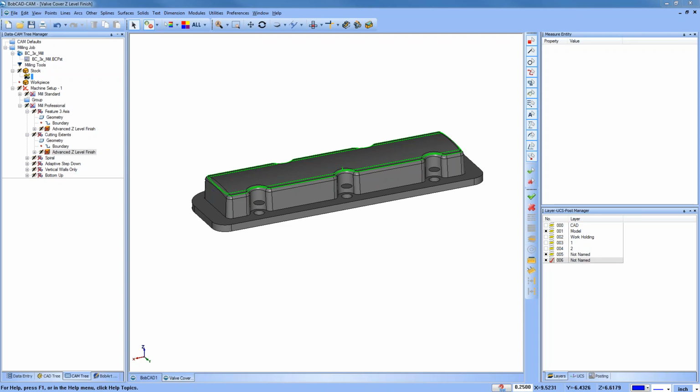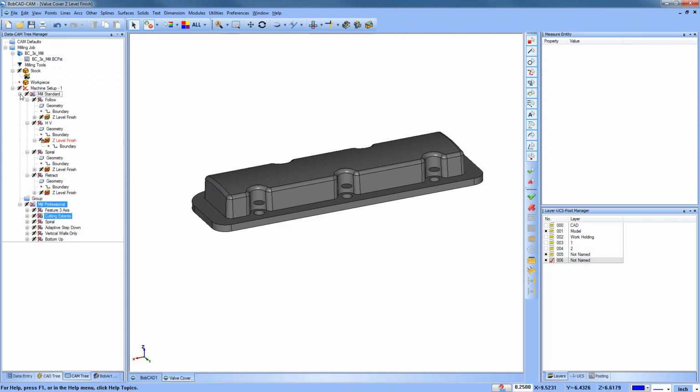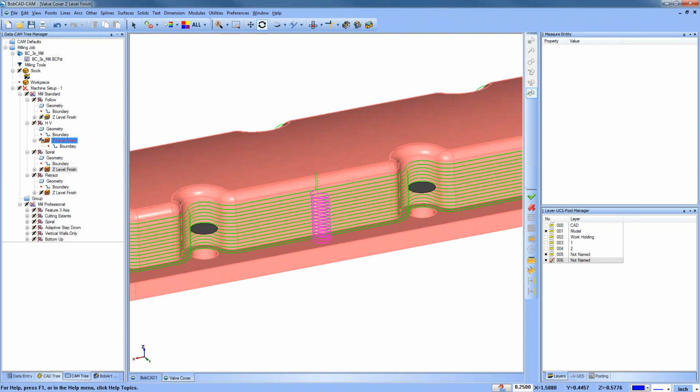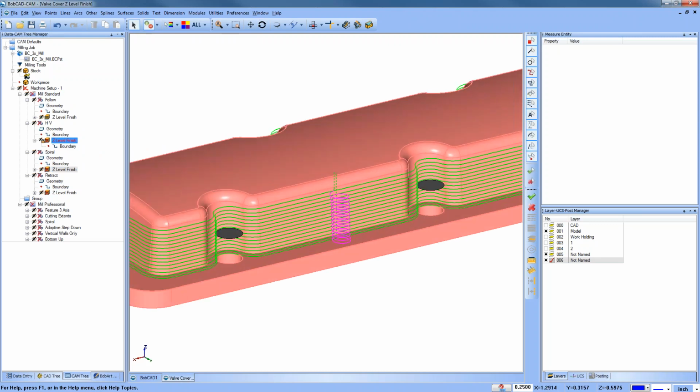Hey, I was trying to program something over the weekend, and ideally I wanted to use cutter comp and be able to loop the levels of the cut, cancel cutter comp and swing a loop like what you're showing under one of your 3D toolpaths, the spiral lead in and lead out. Is there a toolpath that'll use cutter comp and spiral off of that level and spiral into the next one?